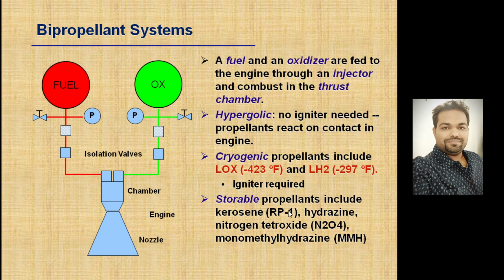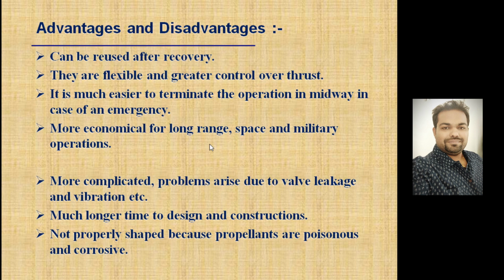Storable propellants include kerosene, right? RP1, hydrazine, nitrogen tetroxide, right? And monomethyl hydrazine, right? These are the commonly used. And LOX can be used as oxidizer, right? Both will be in liquid form in the case of bipropellant.